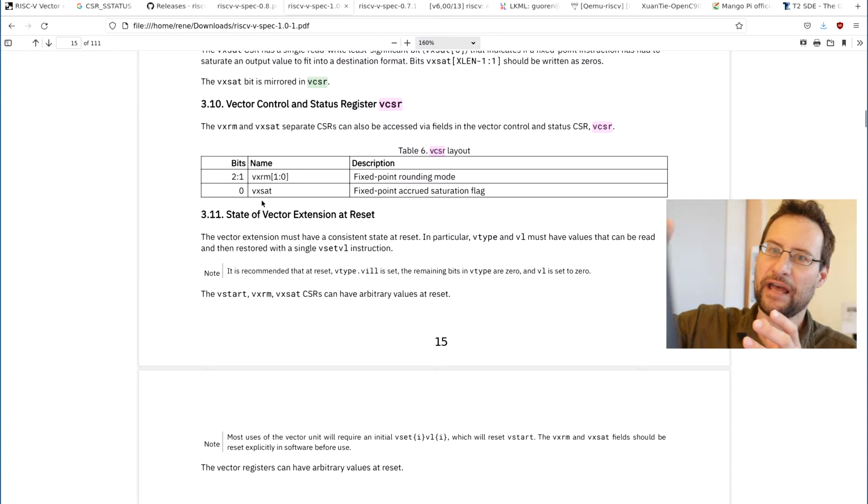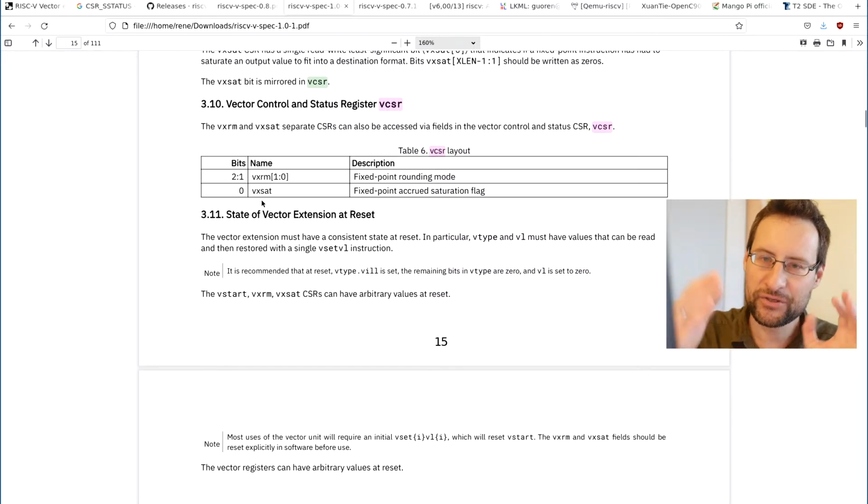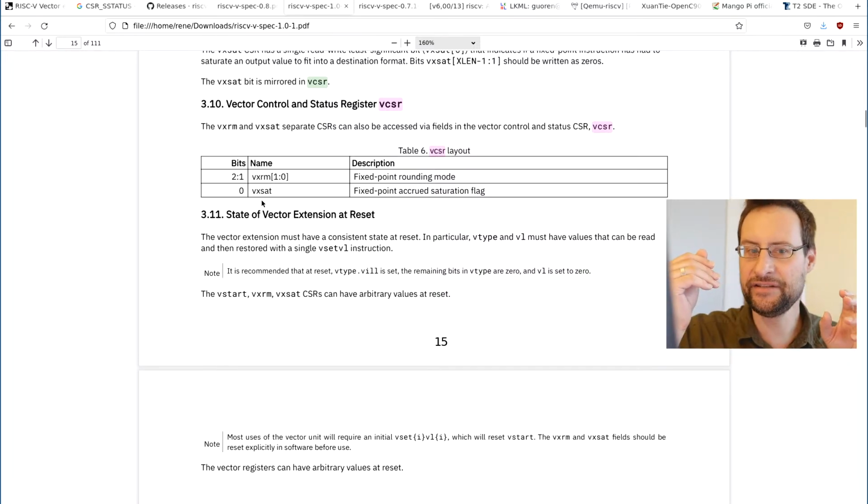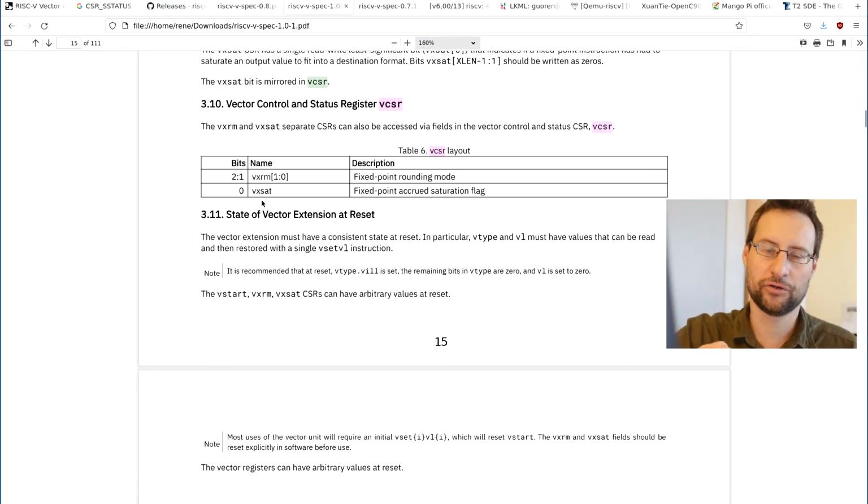Like you are adding values, working with image and audio data, you add 2 numbers, like you have 8-bit numbers, they go from 0 to 255, binary stuff, right? And so you add stuff and normally, like in old-fashioned microcontroller integer stuff, that would overflow, right?